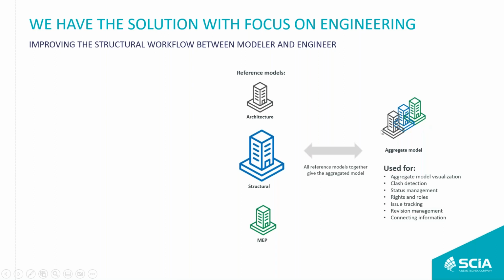We can use this CDE platform for clash detection and for status management. We can assign rights and roles to whoever is participating in the process. We can use it for issue tracking and revision management of the models. And also we can store the information in one place, and this information is, let's say, a bit better than simple PDF files. For example, we can add metadata to anything, and it's great for the cooperation and the whole construction process.